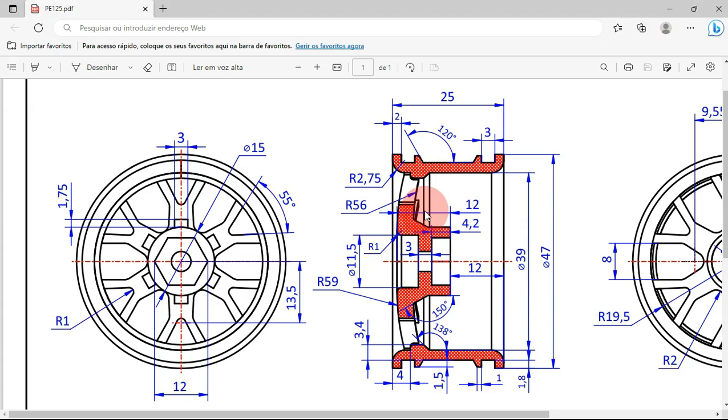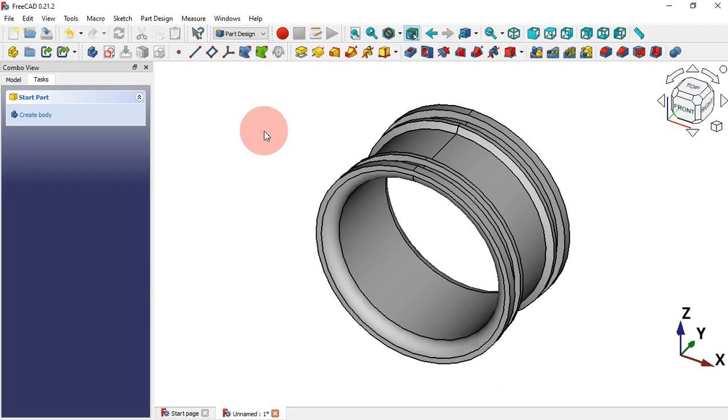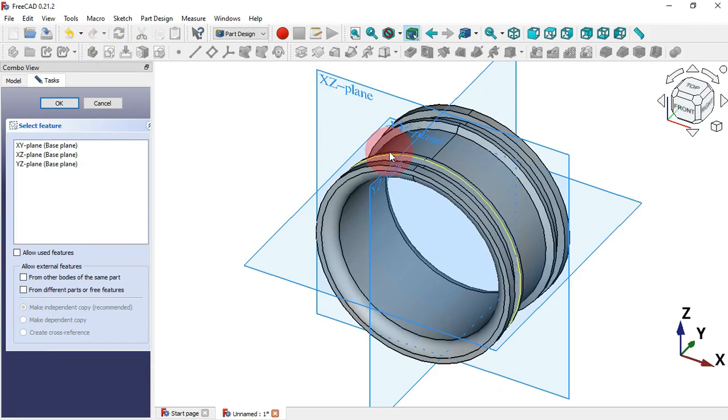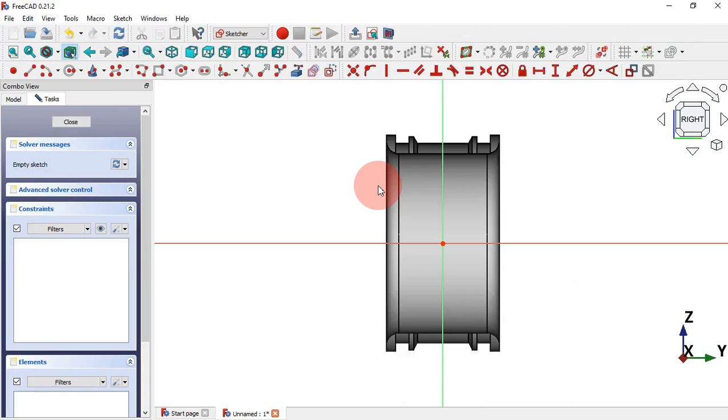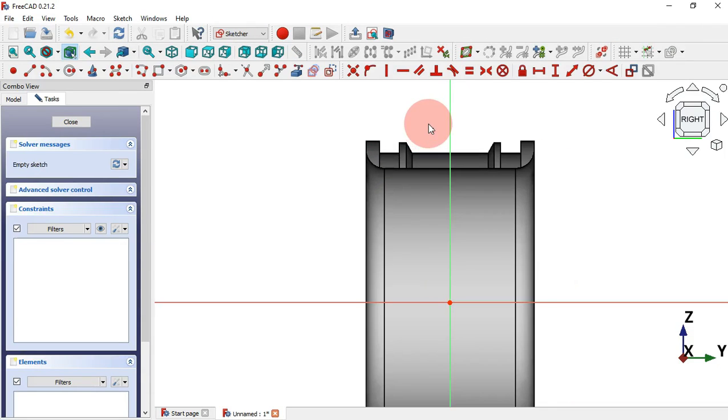Okay, the next thing to do is to create a sketch in which you'll draw a section of this sketch here, this sketch, without this part here. So again, we click on this icon to create a new sketch, and we select YZ plane again. Okay, now what you do, we go to sketch geometries, and we need to select polyline tool again. Okay, let's start by this horizontal line, and next this